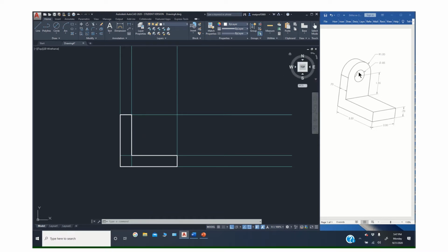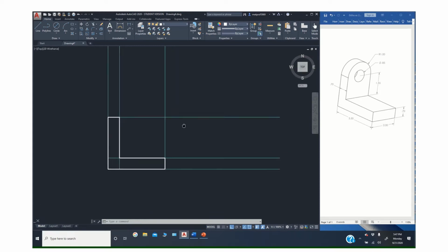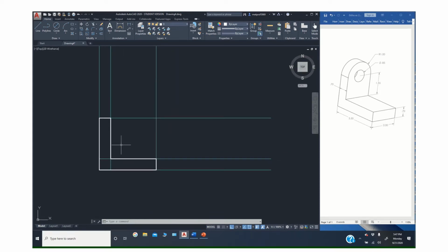Okay, so now we are going to have to locate that hole. Let's go to our right side view and then we'll come back. It's a lot easier to draw a circle and then project lines. Let's go back to our construction layer. Let's offset. Yeah, that's too much space. Let's just leave 2 inches between. Offset 2, enter, and offset 2, enter.